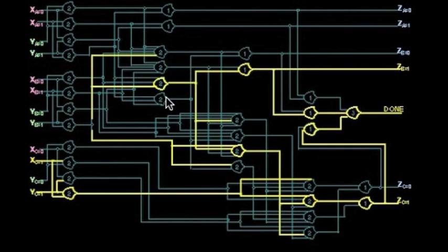Now an orphan path is a branch off an otherwise effective path. This is an effective path because it's observable at the output. This is an ineffective path because it's not observable at the output. And in particular, what's not observable is when this path transitions to null. When this path transitions to null, we can observe it. When this becomes null, we know that this path all the way back through here is null.